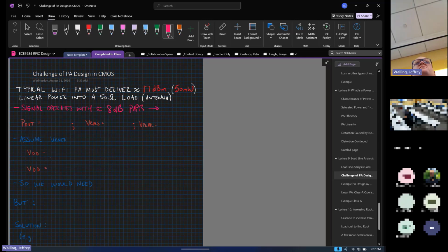This is for the old Wi-Fi standard. What existed in the 2.4 gigahertz band is typically what we would have called 802.11g back in the day. And the maximum modulation encoding standard for 802.11g was a 64 subcarrier, 64 QAM OFDM based signal.